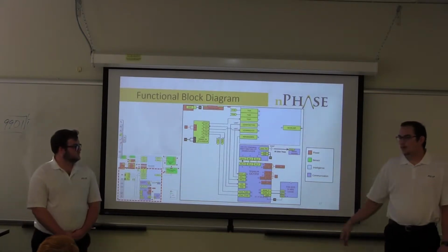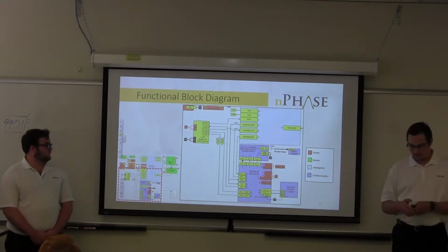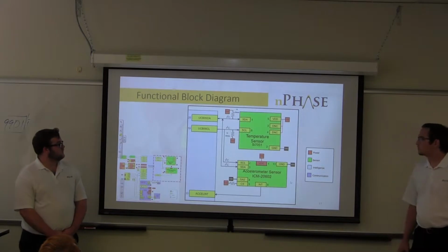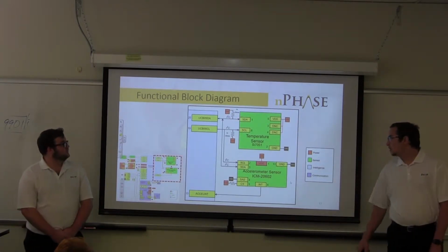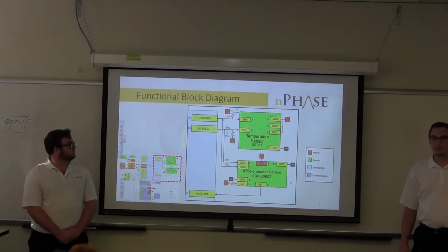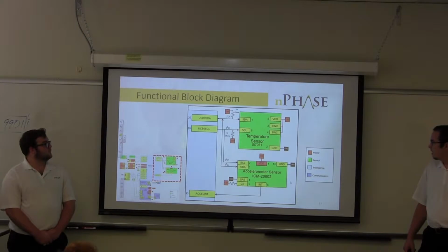We also have a 24 megahertz crystal that's going to be connected to our CC1310. Next, we have a look at our I2C sensors. They're sharing the exact same 2 I2C lines, and they'll both be pulled up with 1 kilo ohm resistors.